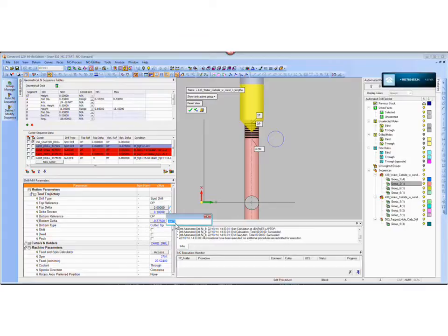But I put a condition in here that says only allow this to happen if the hole depth is more than 2.2 in length. What's our hole length? We can look up here and we can see it. It is 11 inches. Okay, so if the hole were more than 2.2 inches, then I want to do the pilot